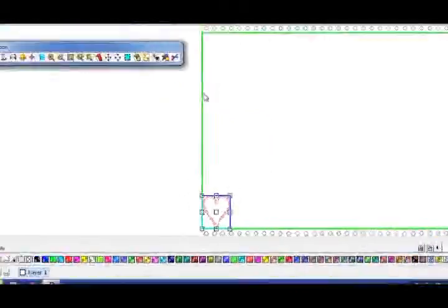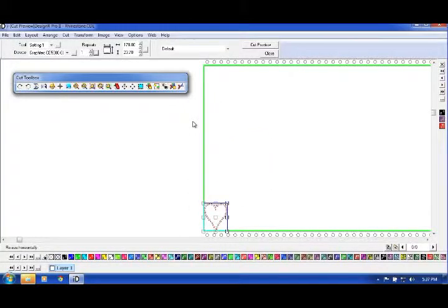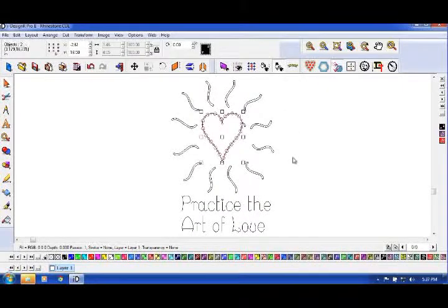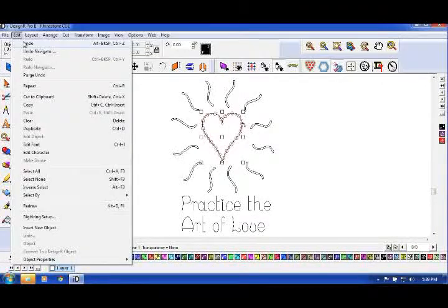shapes. Keep in mind that if you draw a special shape in the workspace that you'd like to use for a rhinestone, the software will not recognize it as a rhinestone. Only the rhinestones taken from the Rhinestone Elements library supplied in iDesigner Pro 2 will be recognized. We will talk about how to remedy this in just a moment. Let's undo this and start over.